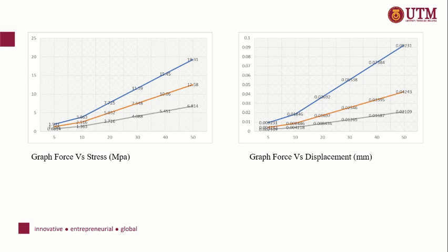From this graph, it shows that 10 mm thickness creates bigger stress and displacement changes compared to the other two dimensions, which are 12 mm and also 14 mm. I purposely gathered the whole stress in one graph, and the other graph is the whole displacement, so that it is easier to see the difference for different thickness of the steel arm.